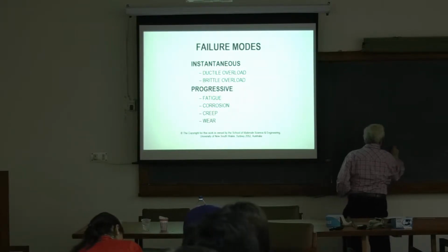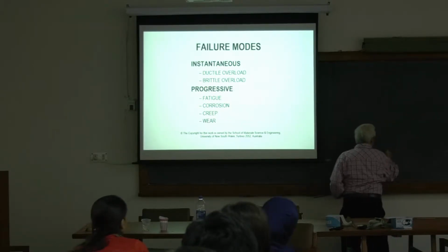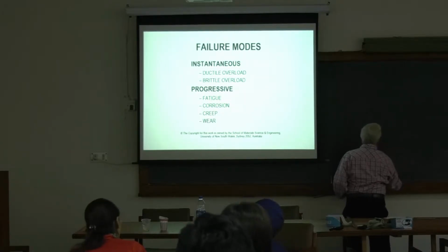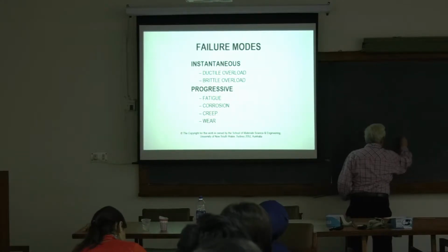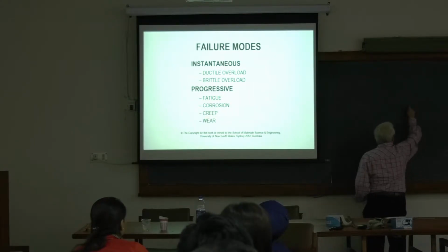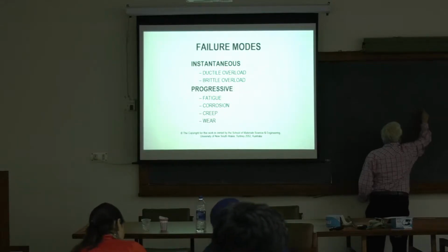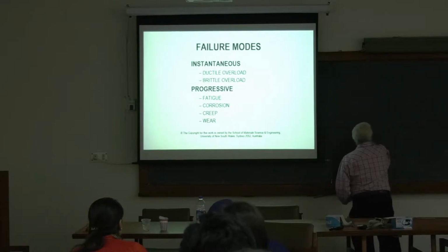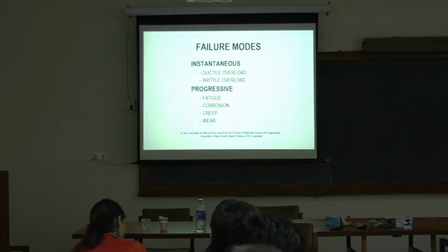So initially it may go up like that, and it may take a long time to progress. As the time goes up, the deformation will go up. This is the creep going up. After some time it can flatten, or in some cases it might even go and fail. So this is failure. Creep is under constant stress.